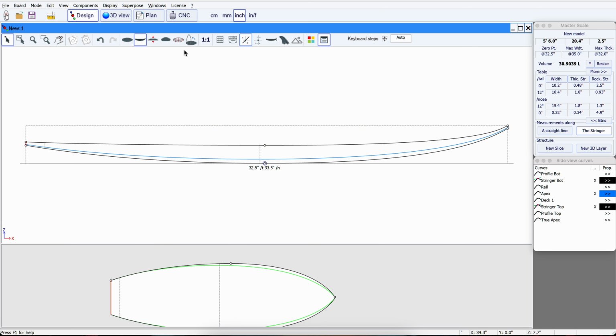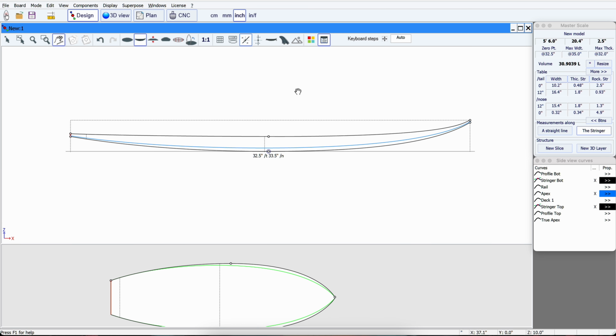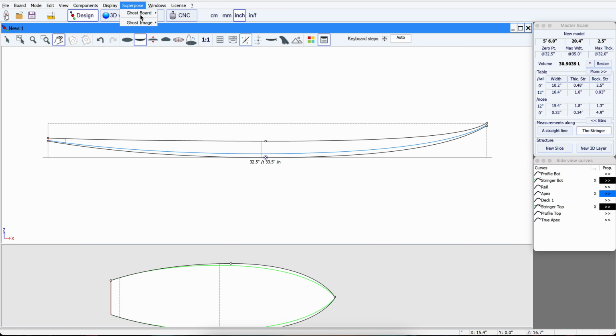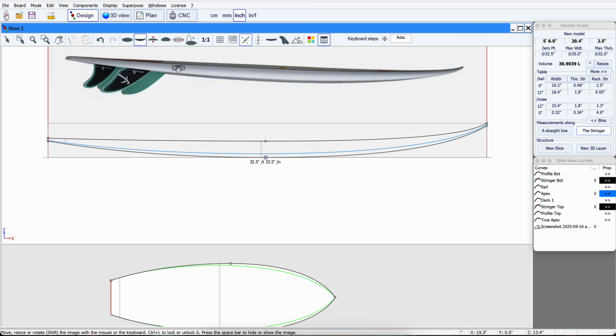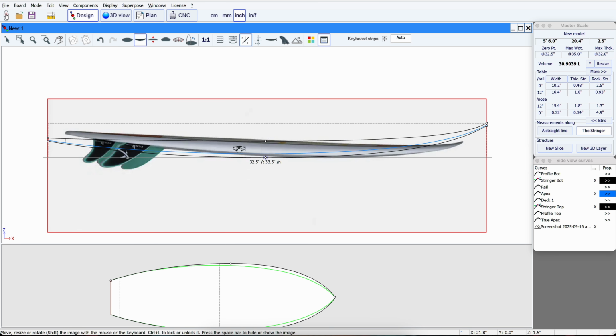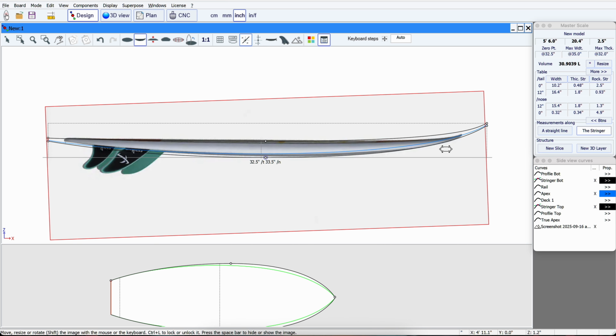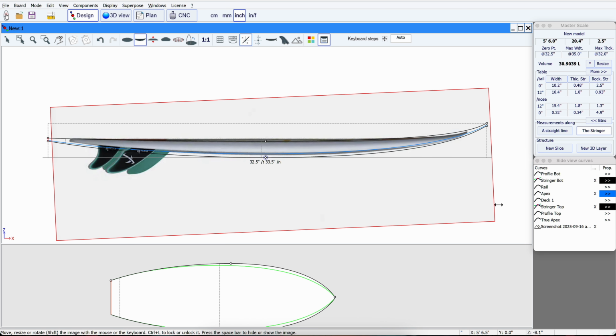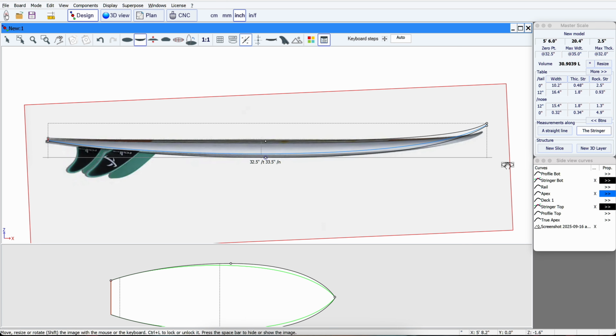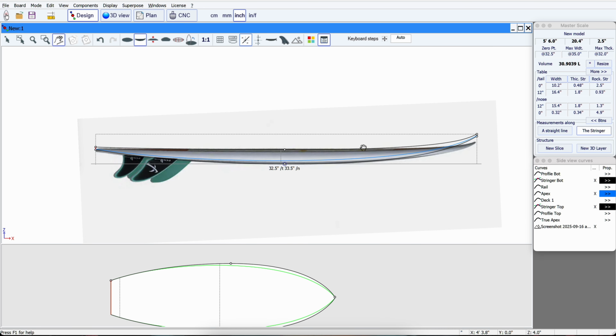And let me close that image. And again, you want to do exactly the same thing. So ghost image, load the ghost image, and you want to open the rocker. You can see it's not really fitting. I'm going to click shift so I can rotate it, as the image wasn't perfect. And I'm going to roughly scale up the board to match with the photo. And again, do not really worry that it is slightly thicker here. That's okay. You can match it, up to you, but I would just stay around something like that. Cool. Go, lock the image, and start to work on the rocker.